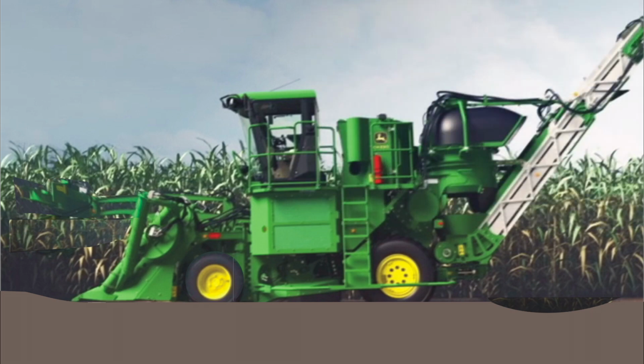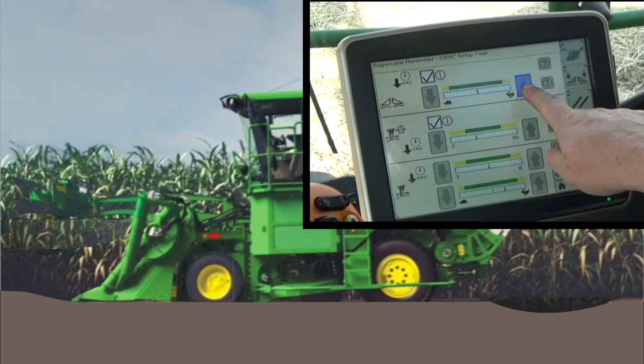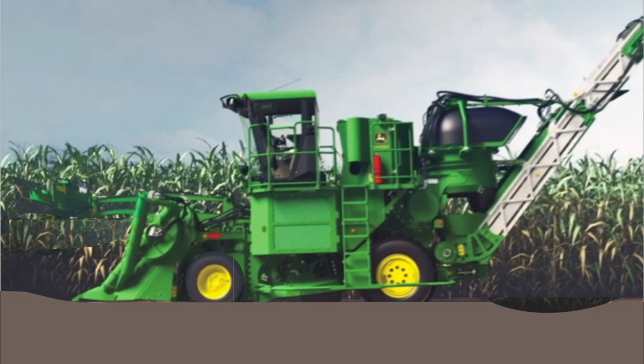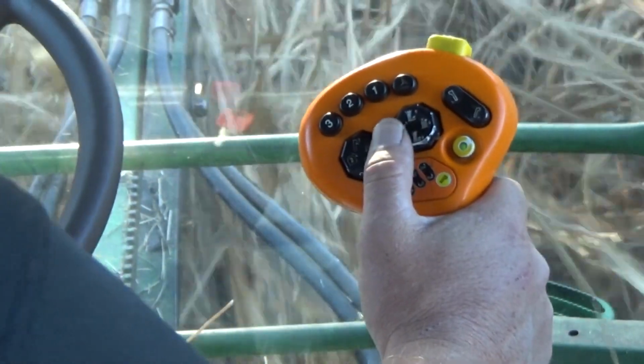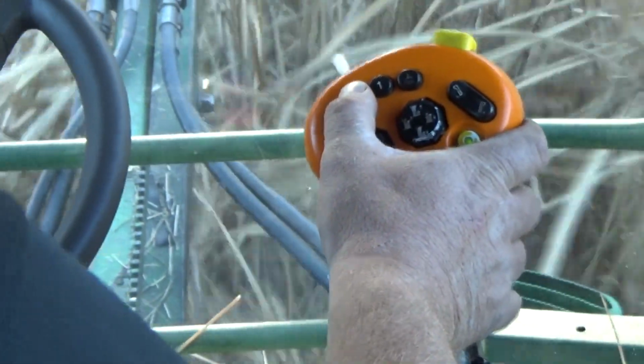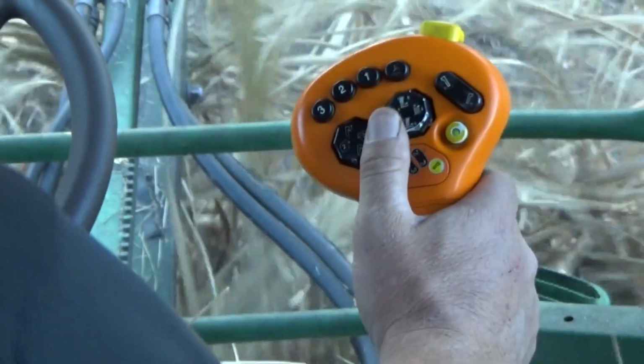control performance. If down cane or high stubble remains in depressions in the field, raise sensitivity to allow the crop dividers and base cutter to better follow the contour. Higher sensitivity settings may result in continual crop divider or base cutter activity, which may be felt by the operator. A balance between consistent surface contact without unnecessary height control action is the optimal sensitivity setting.